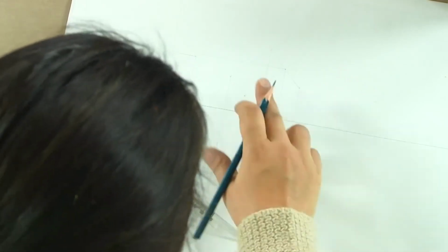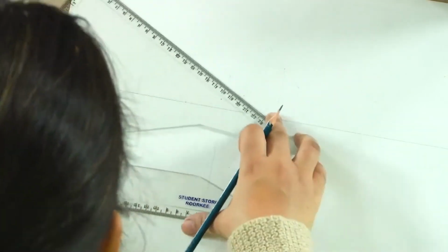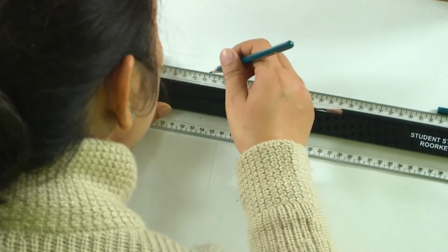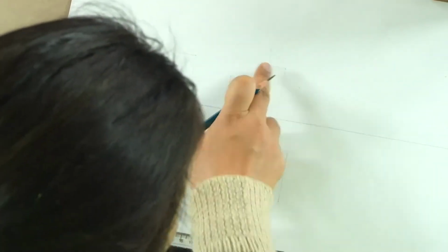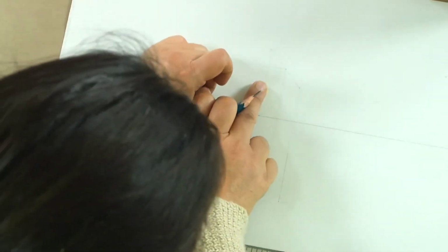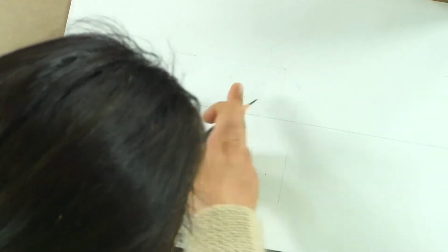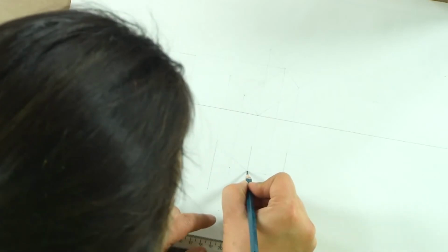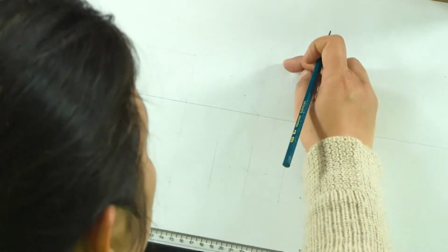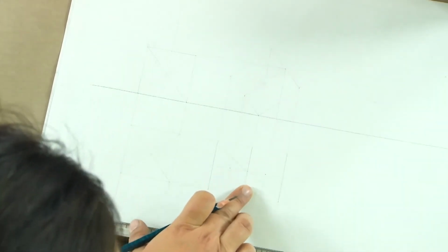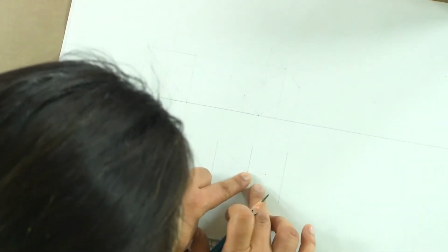If you look at this, this is the midpoint of the axis in elevation. So this is our reference line. Half of the axis is inclined about this point, or probably this entire axis is inclined about this. Further, when we incline it, this is going to be the point, and this is the 30 degree line. The trace of this is going to be inclined at this 30 degrees.